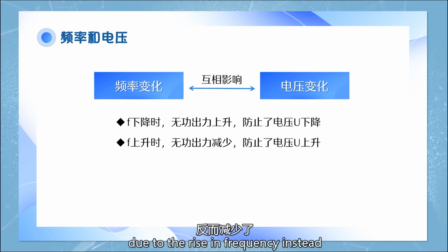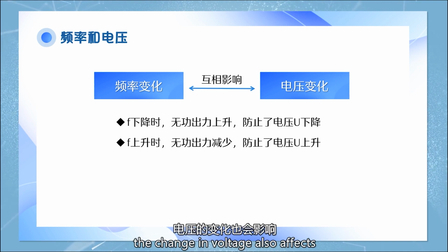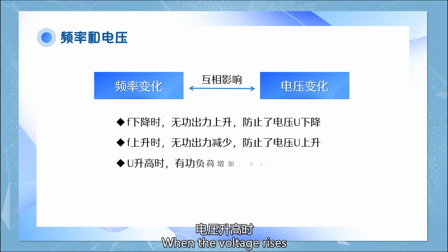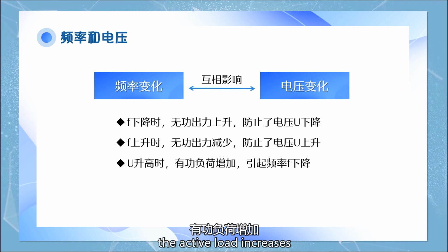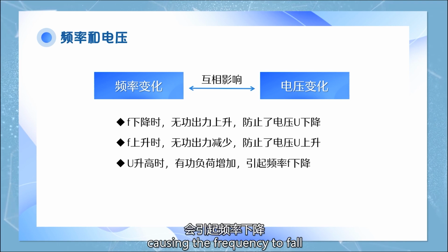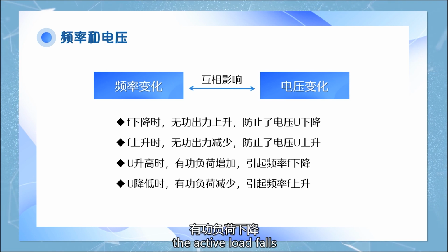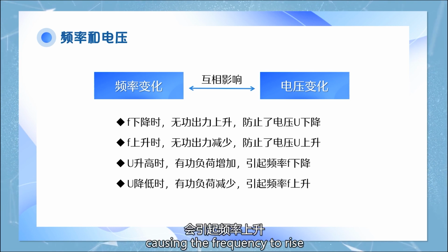Likewise, the change in voltage also affects the system active load. When the voltage rises, the active load increases, causing the frequency to fall. When the voltage falls, the active load falls, causing the frequency to rise.